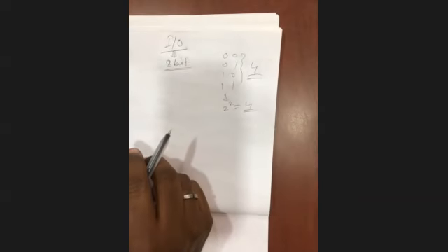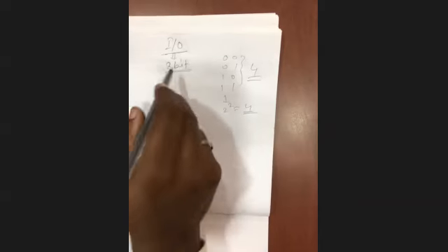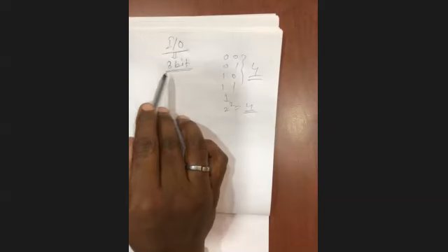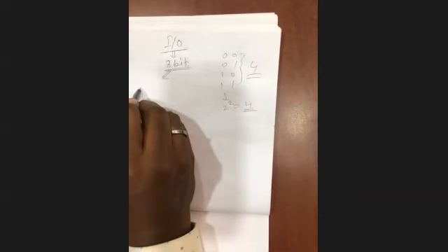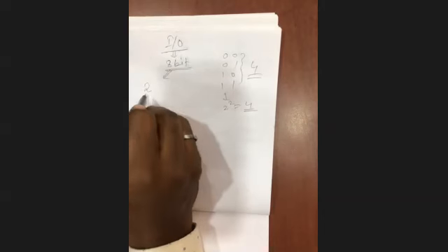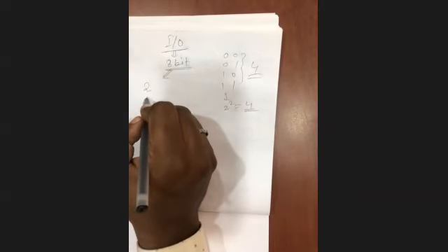And in hexadecimal, we can go up to 99. Here 8 bit has been said, so it is binary. If it is 8 bit, how many addresses can we generate? 2 to the power 8, which is 256. I can generate 256 addresses using IO mapped IO. The IO address is 8-bit wide.